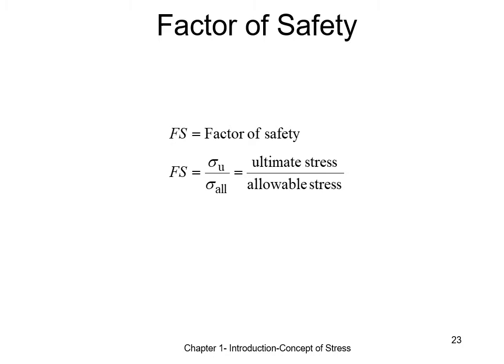Another concept you need to know in this chapter is factor of safety. This number is a multiplier for the allowable stress before the object will fail. If your object fails at say 10 Pascal, this will be your ultimate stress. You will not want to have loaded it to 10 Pascal because it will be at the borderline of failure. Instead, you will want to set a factor of safety to allow you some buffer. Say if you set a factor of safety of 2. As such, it will only allow the object to be loaded by 5 Pascal so that you have some distance away from failure.